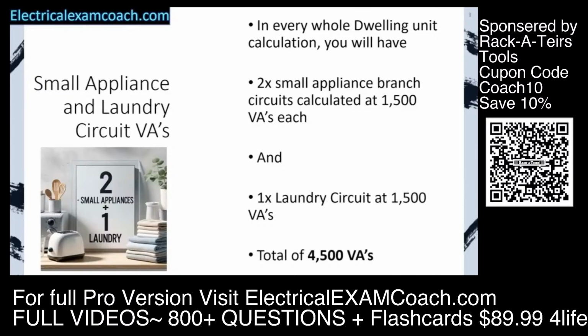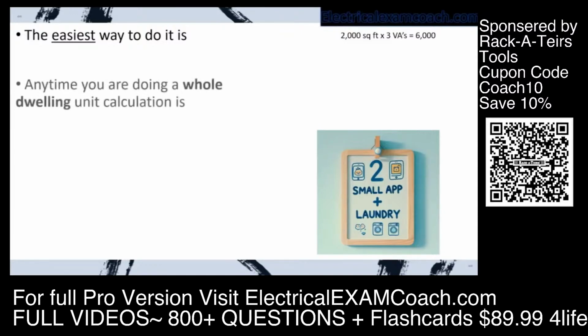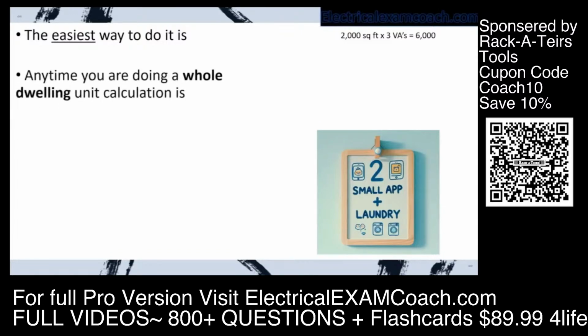Now this is something that we're only going to do and attach it to the general lighting load and receptacles before demand factors. We're only going to do it when we're doing a whole house load calc. We are not going to add it on to something like an individual dryer or an individual range. Those are calculated individually. This is only when we're doing a whole home load calc. And once we start doing them, I will make sure to reiterate to you so you understand when and how to apply this.